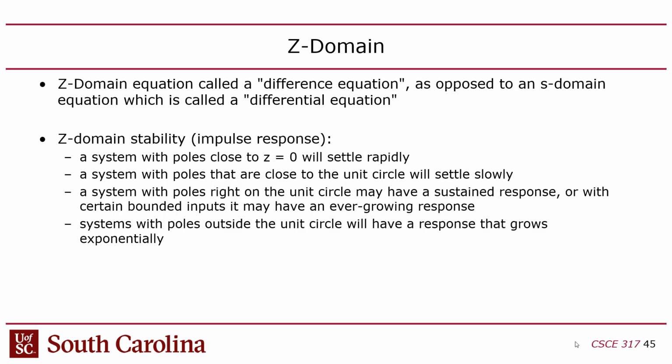But with Z-domain, it's not quite that straightforward. You can calculate poles of a Z-domain transfer function, but you can have poles in the right plane and it'll still be a stable system, but the settling time will depend on how close those poles are to the origin.